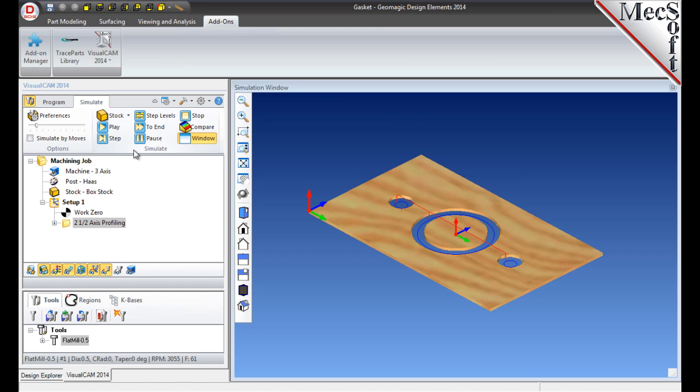To view the cut model with textures applied, select the Material Texture Visibility icon located at the base of the machining browser. Now we'll turn our attention to machining the outer profile of the part. Again, we will create a simple profile toolpath, this time around the outer periphery of the part.